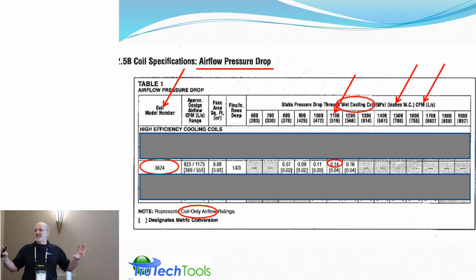Now all you have to do is look at that line and get a ruler out. This will make it a little bit simpler. That'd be a good exercise for students to do. Show them how to read these kinds of charts, show them a couple of different charts so that they're familiar with it. Say you get a reading from your digital manometer or your slack tube or your incline of 0.14 inches or thereabouts. You can say it's about 1100 CFM.